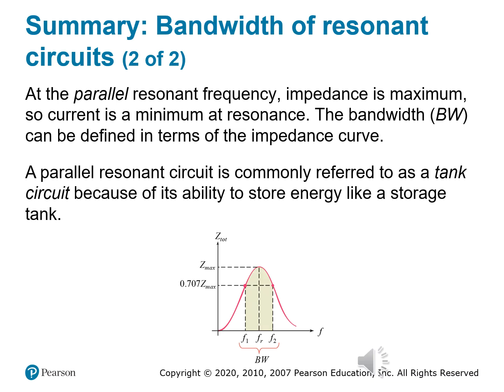And again, just like before, we still care about the bandwidth, but now it's defined in terms of impedance and not current. We're looking for the frequency range where the impedance stays above that 70.7% of the max value. So again, same thresholds, different variable.